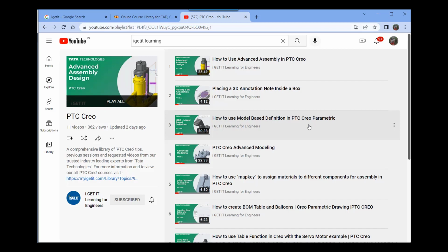As the paperless activity increased, due to the virtual world, these OEMs tried to go to paperless work. They didn't want any kind of a 2D drawing in the form of PDF, and further the print of that 2D drawing on any large sheet like A0 or even bigger, and referring to that sheet to manufacture the parts. So instead of that kind of a process, they started to create the drawing information onto the 3D model only, instead of a 2D drawing. That is nothing but the concept of model based definition.